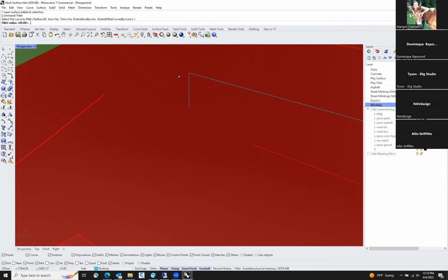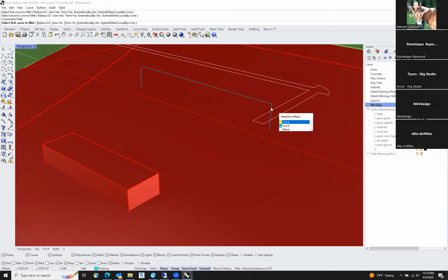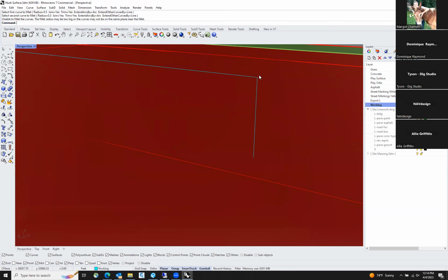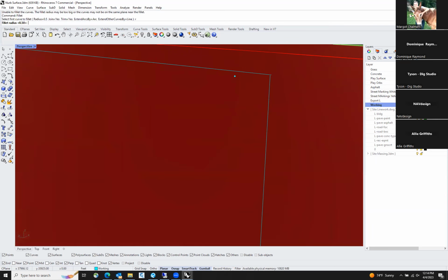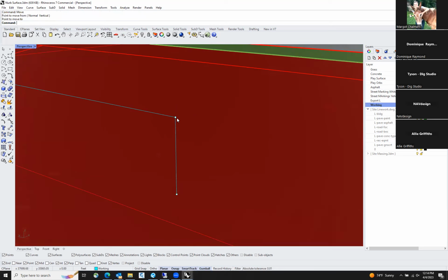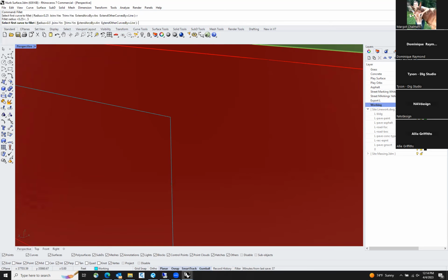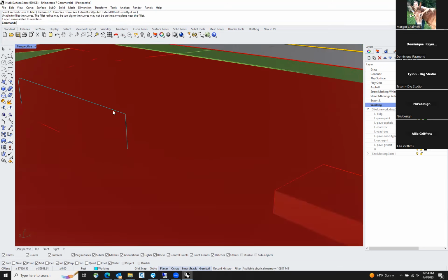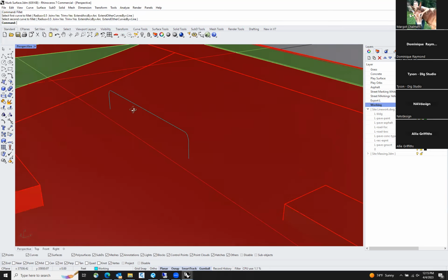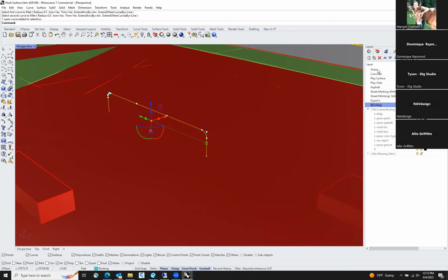And then fillet it, and the radius to 1/2 foot, 0.5. And I'm going to fillet that line. Unable to fillet it. Make sure that it's on the end point. There. So now we have the 2D line that'll make up the 3D railing.